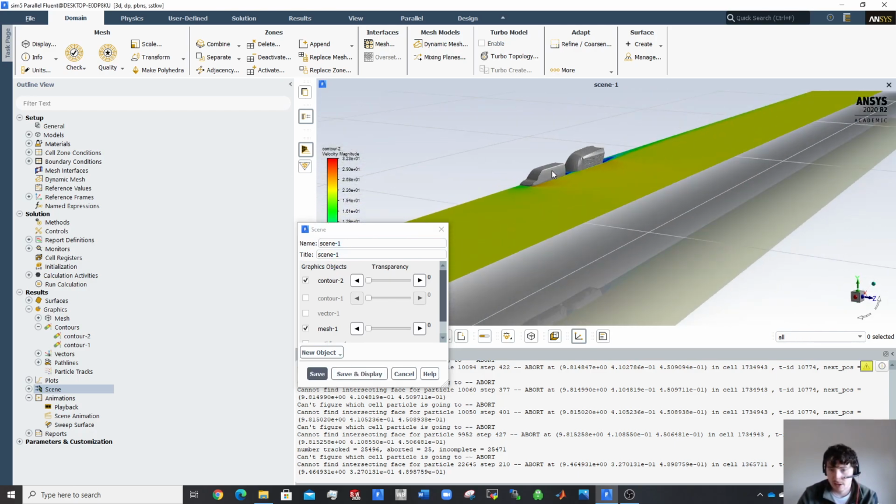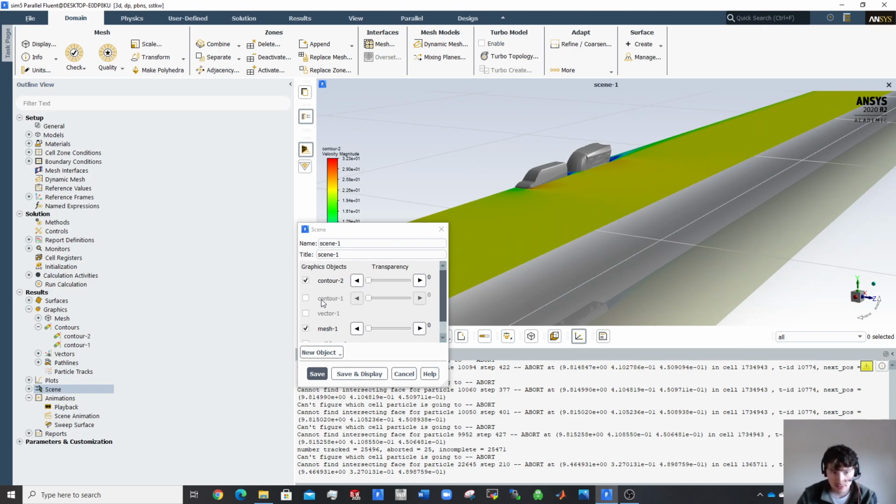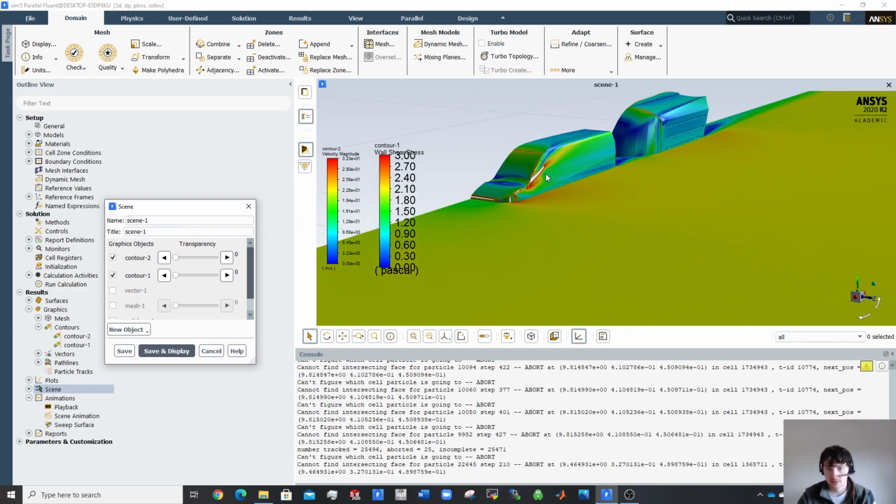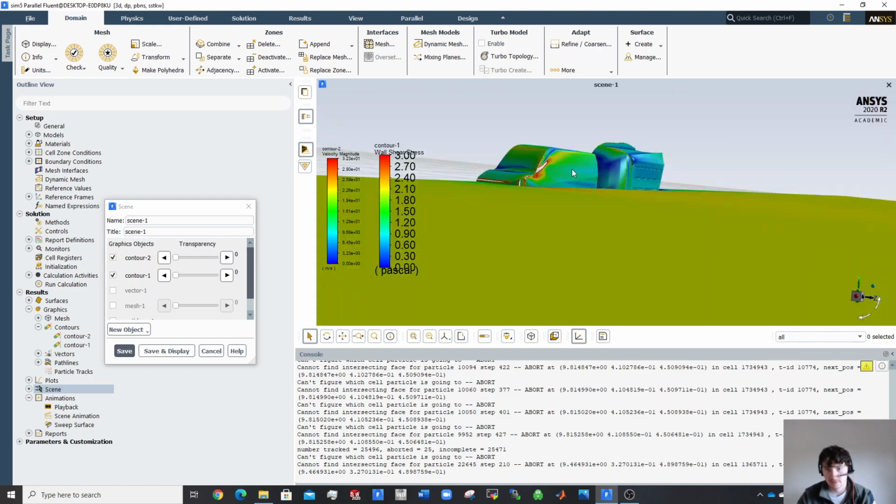So if I wanted to have a pressure plot on that and then a velocity along the symmetry, I could do that. So let's just see what this does. I don't know what that other contour plot was left as. Left as a symmetry or whatever it was left as. We'll see here, hopefully. Just give it a pause. Yeah, so it turns out that other contour plot, we left it as a wall shear stress plot, and so I had to turn off my mesh there so that we could see it. But you can see the idea there of how you can have multiple things showing.